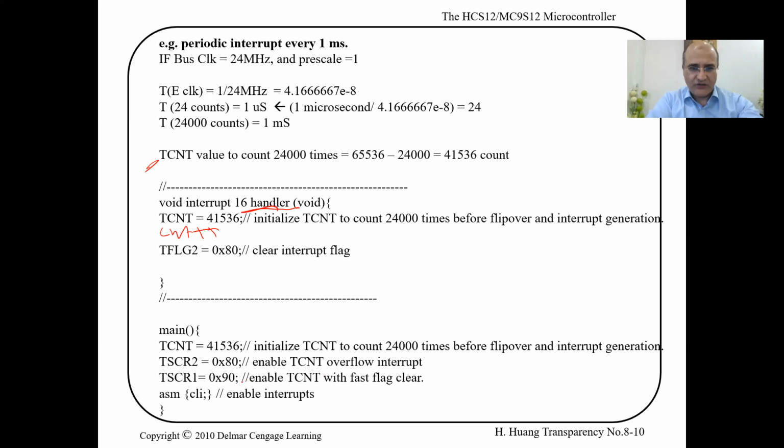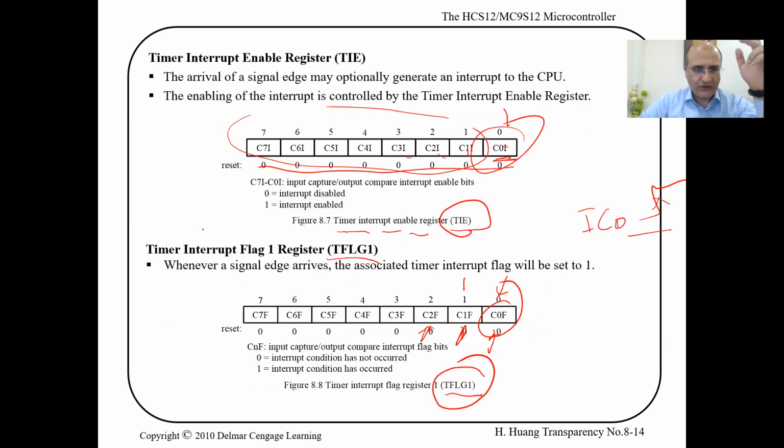The prescaler, I don't remember what it was, but you can configure it. It was 1. You can use a prescaler to make it count slower, and every time you count, increment a counter, call it the overflow counter.